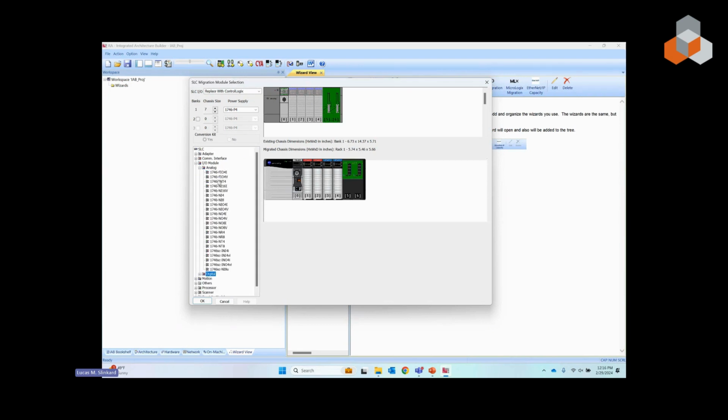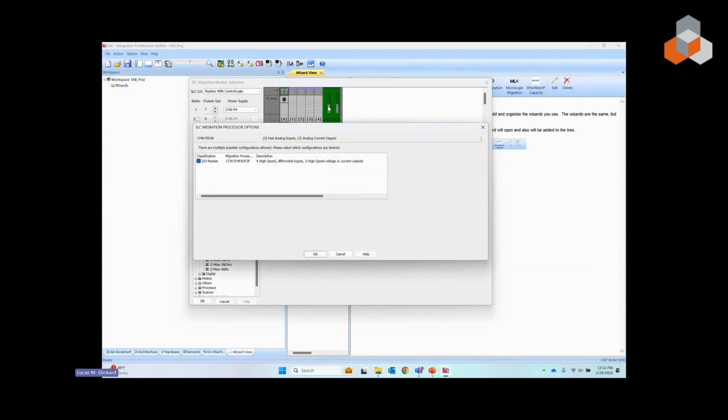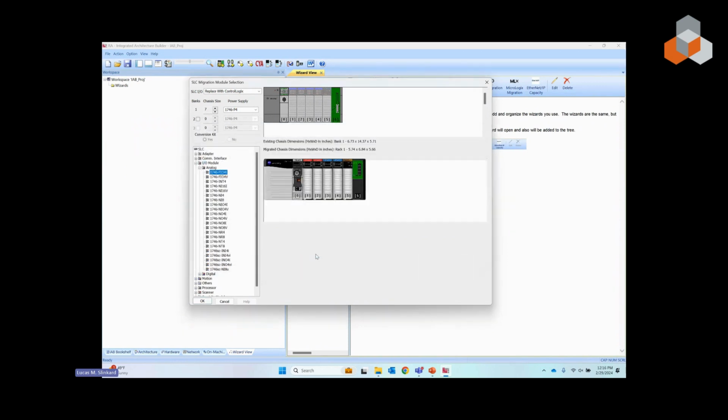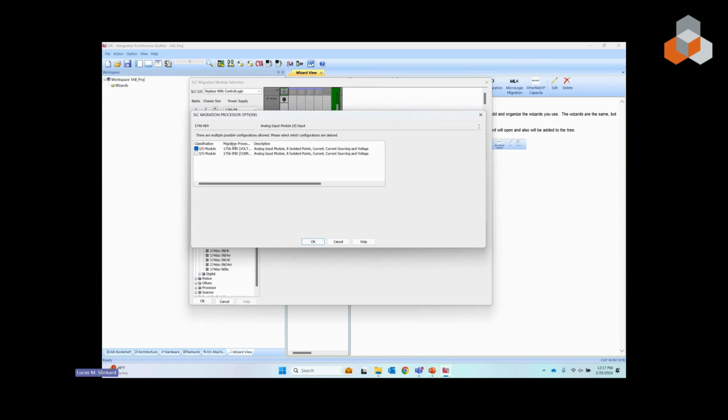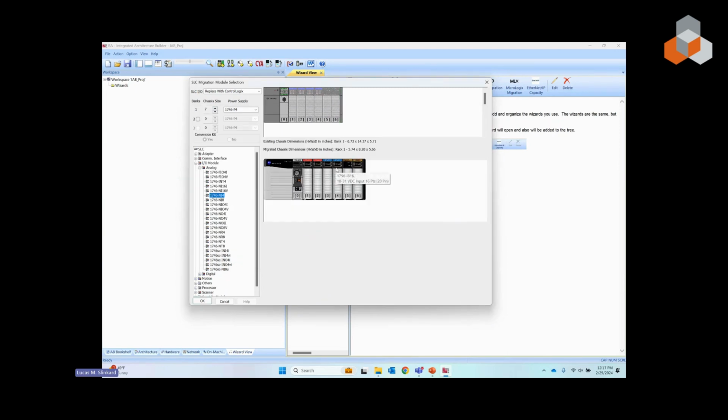The last thing, maybe we have some additional I/O, maybe some fancy cards there. We click, it's going to have the most compatible configuration right here. We'll select OK. Maybe the ever popular NI4. Now we have a selection to make. Are we using current? Are we using voltage? For this one, I know it's current. We make that selection and click OK.